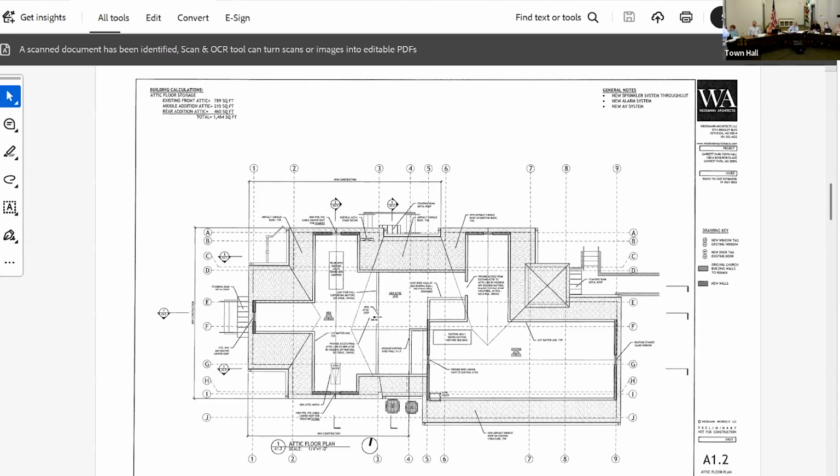We're going to take it down to the sheathing, which we've discovered is a diagonal sheathing applied to these walls. We're going to put a weather resistant air barrier on top of the sheathing, and then a drainage rain screen mat behind the new siding. That will allow it to dry out properly. You won't get the same performance of the paint that you've experienced over the last 50 years. Because this is a historic building, wood will be used in the replacement here. On all the new work, both the siding and the trim will be a cementitious material, like a Hardie plank, but thicker than Hardie so that it looks more authentic.